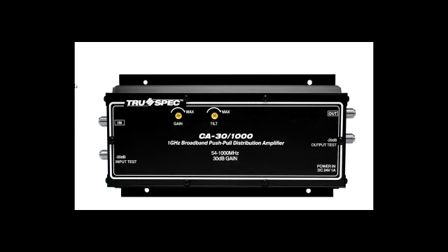And then the tap would be a less attenuating tap that is supposed to deliver the signal to the television set. Right? So that's basically how it works. So the signal that is coming into the amplifier here has to be adjusted to a certain strength so it has enough signal to carry to the furthest point. Right? And then the taps would be chosen accordingly to deliver the signal strength to the TV.